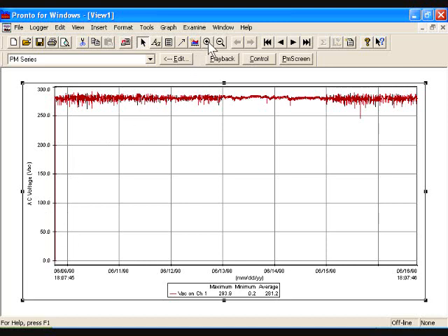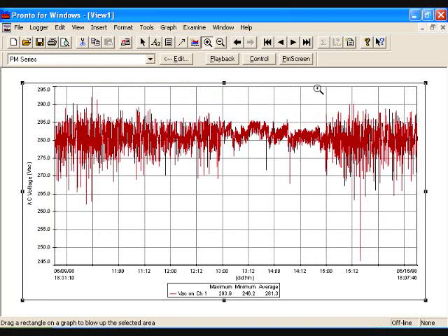However, by using the zooming tool, which is the plus magnifying glass here, if you click on that, you get a magnifying glass, and you can just zoom out the very few first seconds of this recording, and then the voltage will appear as it would normally be presented to your eyes. Now, if I go back to the arrow and pick up my cursor and I touch the graph line now, you'll notice that the minimum is 246 volts, which is what was the reality of it once it was hooked up.